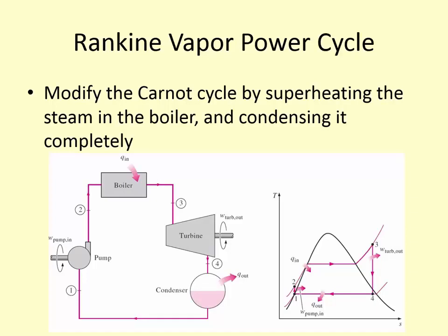Did you have a question, Jajon? I was going to say, for instance, there's one of the pump steam that you're talking about. Well, no, this is the compressed liquid region over here, right? So we're outside the dome. This is liquid. Here, we're pumping up just to the boiler pressure, and then we're increasing the temperature of the fluid. So here it's a liquid, then it becomes a liquid vapor mixture as we're evaporating it, and then we continue to superheat.